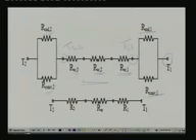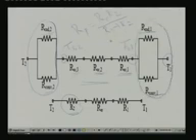And this radiation network, as you remember from your basic electrical technology, can be reduced to this form. What we have done here is that the resistances offered by the radiation and convection of room 2 can be clubbed together because they are in parallel. So you can find an equivalent resistance R2. As you know, for parallel resistances R1 and R2, R parallel is equal to R1 into R2 by R1 plus R2. Here R1 and R2 refer to radiative resistance and convective resistance. So I have reduced this to an equivalent resistance R2. Similarly, this portion can be reduced to an equivalent resistance R1. So we now have 3 resistances in series: R1, Rw and R2. Rw is the equivalent resistance for the composite wall.